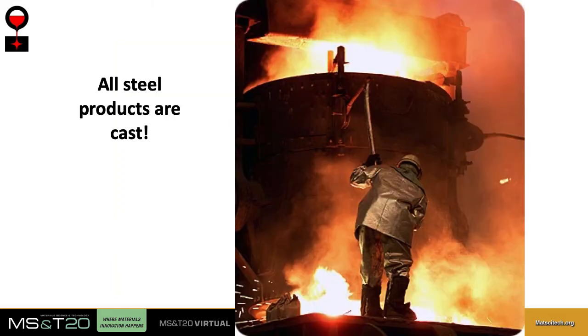There's always the perception that parts fail because of a defect. When castings fail, metallurgical analyses of the part would usually attribute the failure to an inclusion or a porosity. Failures are not caused by defects. It is caused when the part is loaded beyond its capacity.